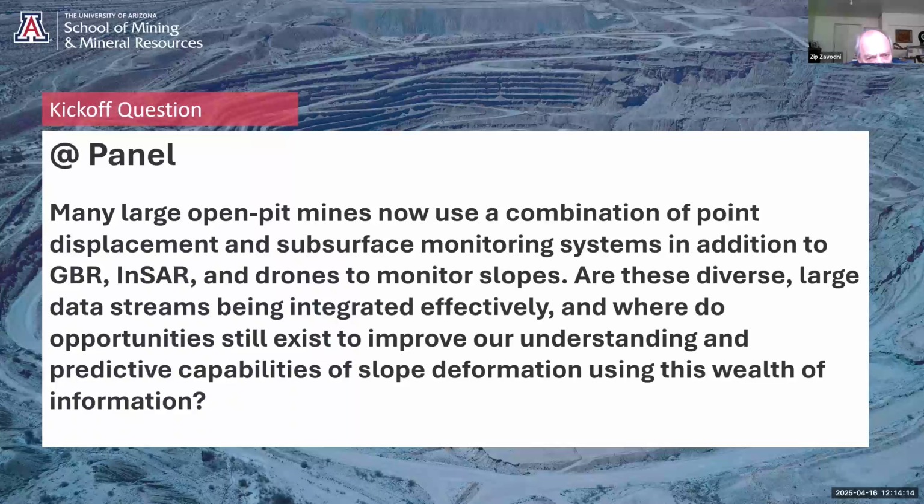And I found over the years that a good extensometer, subsurface unit, inclinometer, shape array, etc., sometimes provides critical information before it's even documented on the surface. So subsurface monitoring is a very important key ingredient input into our science.